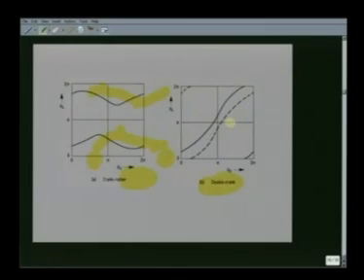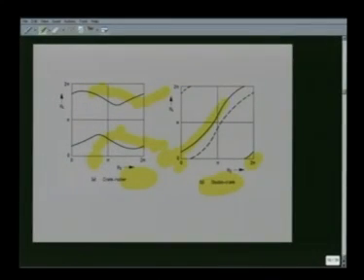This is the typical theta 4 versus theta 2 characteristics of a double crank. As you see, theta 2 goes from 0 to 2 pi and theta 4 also goes from 0 to 2 pi, because both the input and the output links are capable of making complete rotations. But because it is a Grashofian linkage, there are two distinct modes of assembly as represented by this firm line, and the other mode of assembly is by this curved line, and these two curves can never intersect. That is, each curve corresponds to a particular mode of assembly.